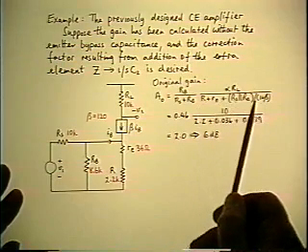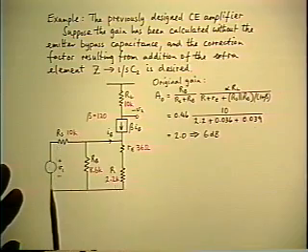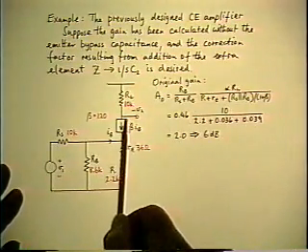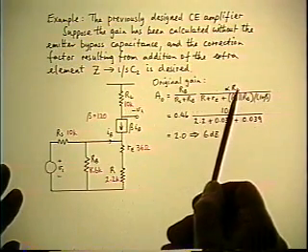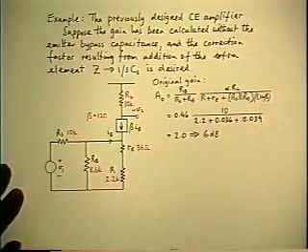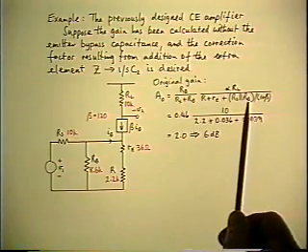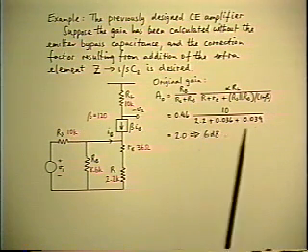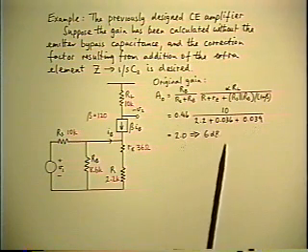Therefore, determining the denominator of this expression, which gives you the emitter current as a function of the Thevenin voltage. Multiply the emitter current by alpha to give you the collector current, multiply the collector current by RL to give you the output voltage, and that's the end. So you've built a low entropy expression by writing the answer in one line. Substitute numbers, compute the answer, comes out to be 2, converts to 6 dB.